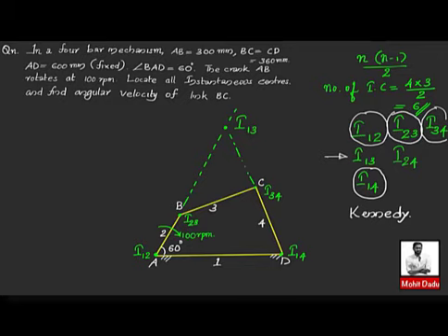Next you have to mark I24, which will be lying on a straight line connecting I12 and I14. One will be going, then the remaining terms will be 2 and 4. So I24. Similarly, I23 and I34. Common number is 3. Then the remaining will be I24. So I24 will be lying on these straight lines which are extended.